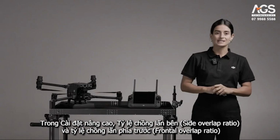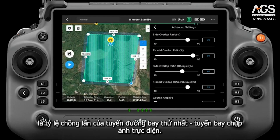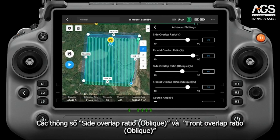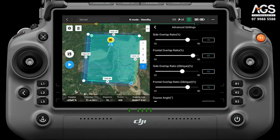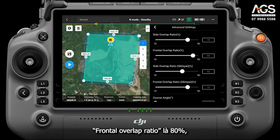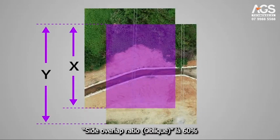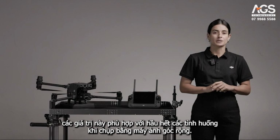In advanced settings, the side overlap ratio and frontal overlap ratio is the overlap rate of the first route, which is the orthophoto route. Side overlap ratio oblique and frontal overlap ratio oblique is the overlap rate of the other 4 routes, which are oblique routes. The default side overlap ratio is 70%, frontal overlap ratio is 80%, side overlap ratio oblique is 60%, and frontal overlap ratio oblique is 70% in DJI Pilot app, which is suitable for most scenarios when shooting with a wide-angle